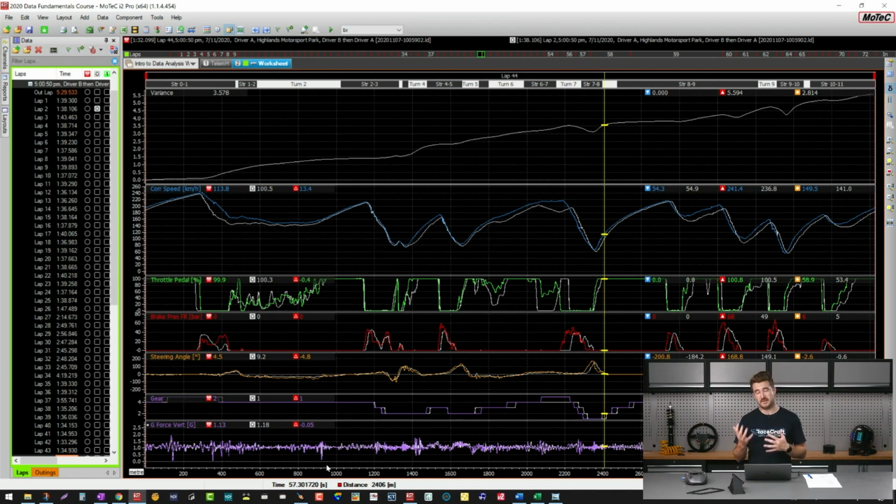More commonly, or in some cases, you've also got wheel speed, which is also used for the speed calculation. Obviously, there are a few potential sources of error, whether it's differences in tire pressures giving you a different loaded radius, or particularly different driving lines as you head around the track. It's going to end up, one car is going to be taking slightly longer to get around a lap. Now, one of the things you've got to be careful of when it comes to doing driver analysis is that you're comparing like places on track.